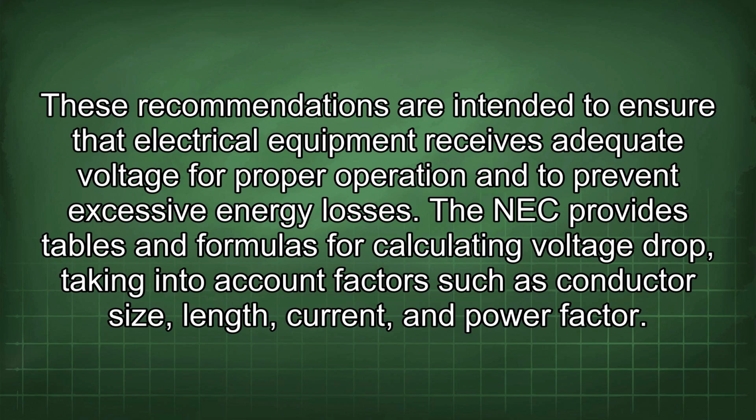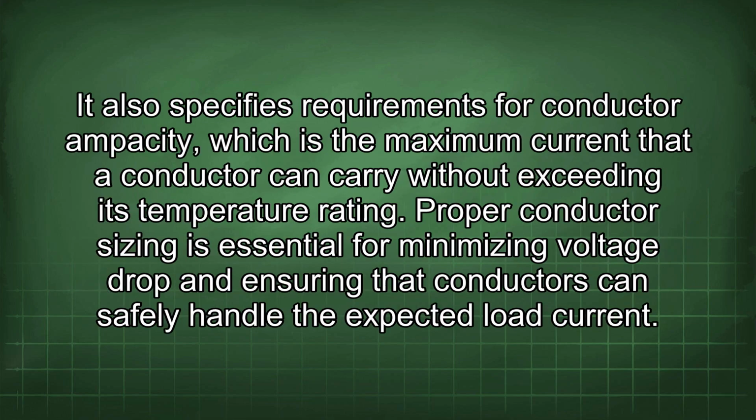current, and power factor. It also specifies requirements for conductor ampacity, which is the maximum current that a conductor can carry without exceeding its temperature rating. Proper conductor sizing is essential for minimizing voltage drop and ensuring that conductors can safely handle the expected load current.